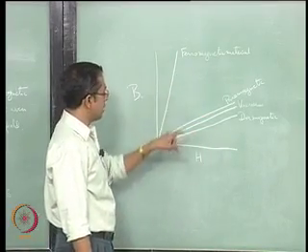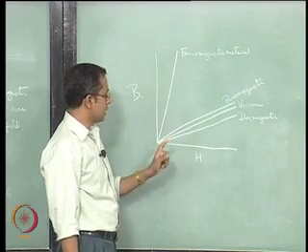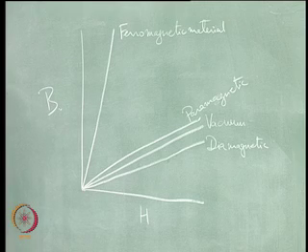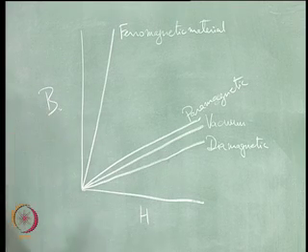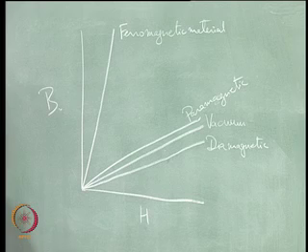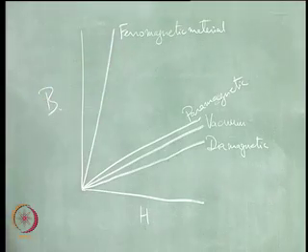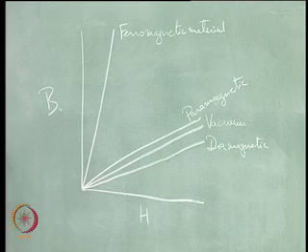And also in the ferromagnetic material the other important thing is if you bring H up to here and then you abruptly switch it off, what you will see is that a fair bit of magnetism remains in the material. Okay, so we do not actually lose the magnetism, it sort of remains in the material. That is the fundamental way in which a ferromagnetic material differs from a diamagnetic and a paramagnetic material.